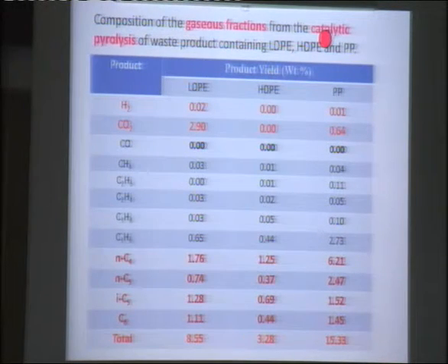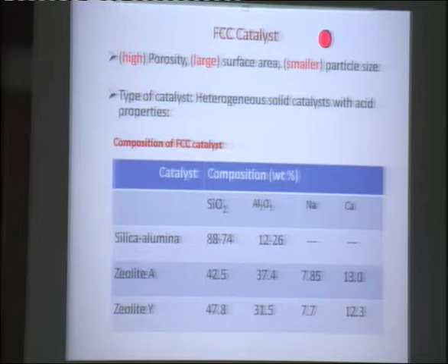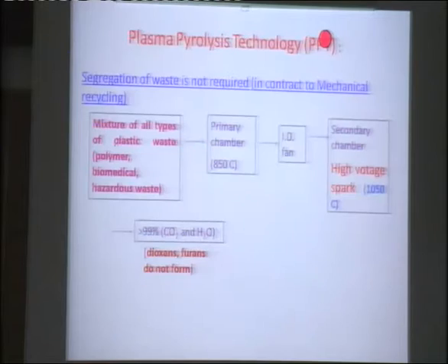Okay? These are the things I was talking about. So next, you have monomeric. You can see from here that if you use thermal cracking, you can crack polymethyl methacrylate 91 to 98%. The polymer will produce back monomer. But polyethylene and polypropylene will not produce it. They will form some other products. Monomer will not form. Okay?